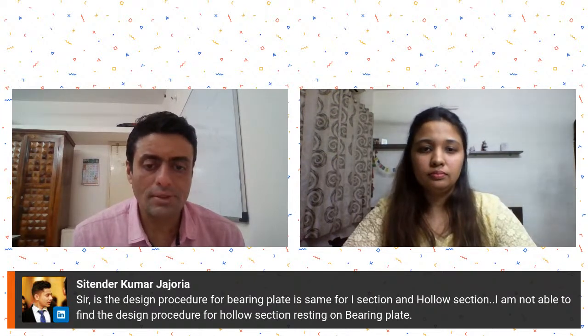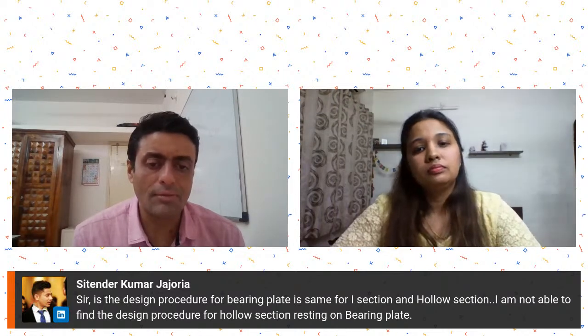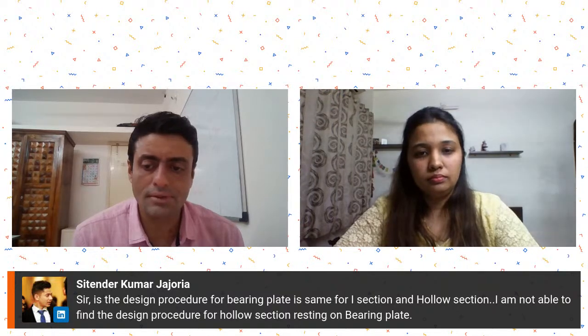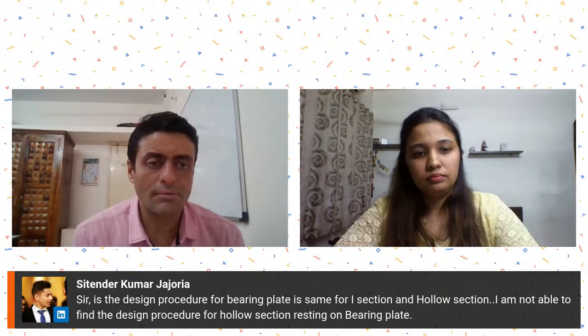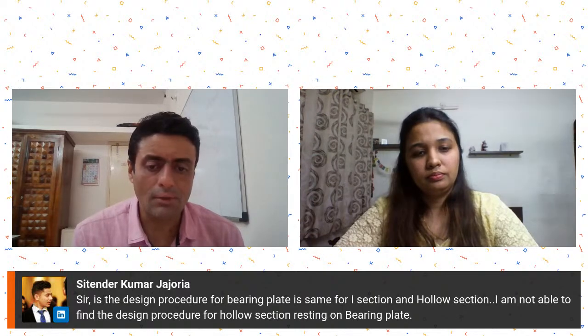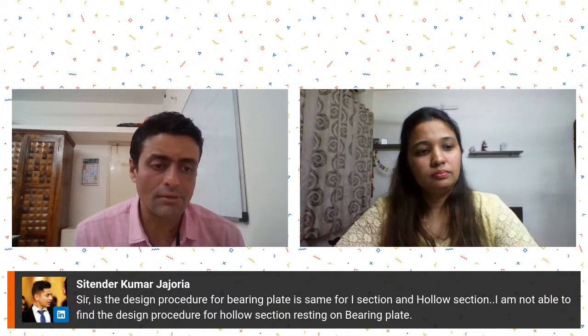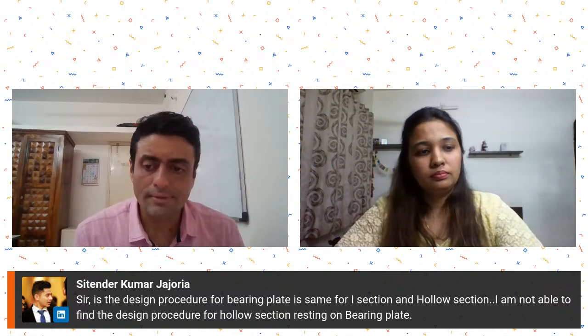So in my opinion, you can halve the reaction from the bearing and divide it over the two webs of the hollow section, and then proceed with the simple checks given in our codes. I at least do it this way. Otherwise, there is no specific method given in any text for doing this.